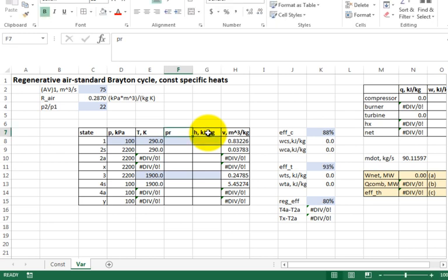Hey, what was the units on this PR? They didn't give any. Don't worry about it. It's dimensionless. It's to do the isentropic calculations. All right. Now, it copied over my color coding, and I don't like that, so I'm going to just clean up that, and boom, there you go. So what you do is you say, I have to go into my table A22 and find P sub r at this temperature. Who has a table A22, and can they find my P sub r at 290? What do you get? 1.2311.